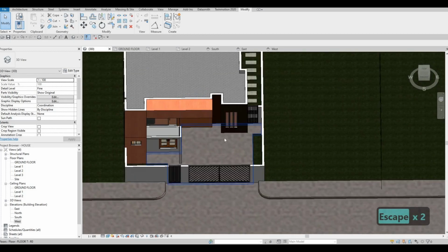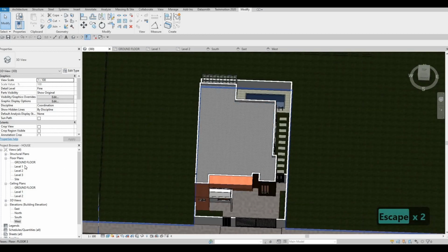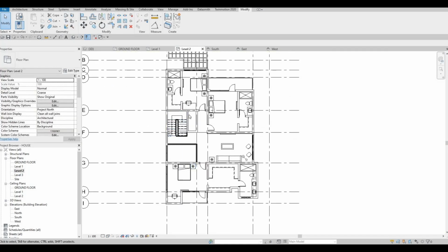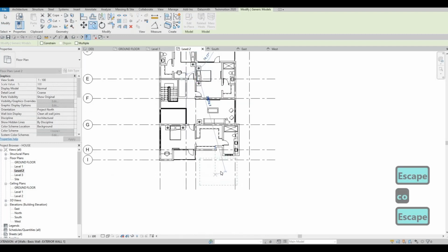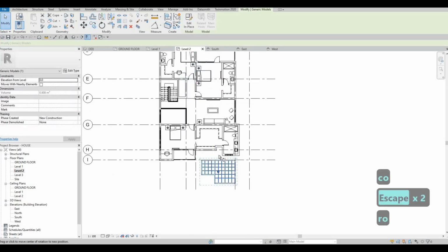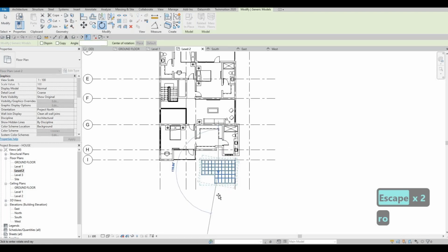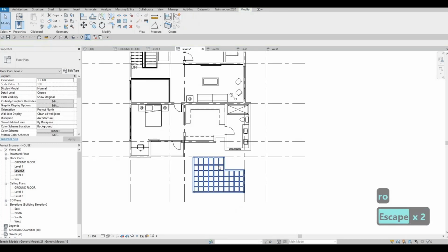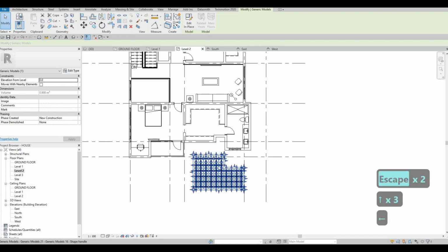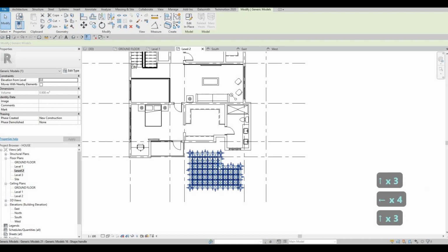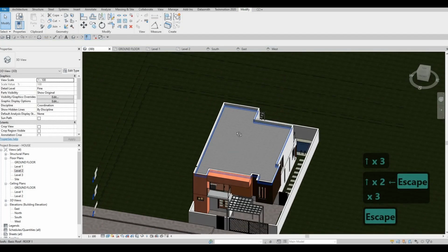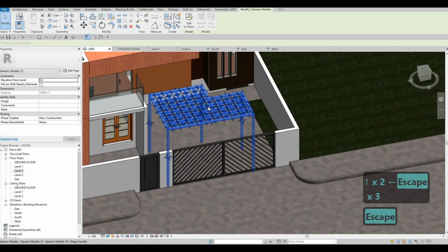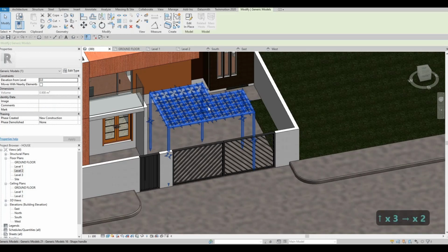before that, I want to extend this part. So here we have, so let's go to level 2. We have this one that we created in the backyard. I'm gonna copy that, and then I'm gonna place it here. I'm gonna rotate it, RO to rotate, and then I'm gonna rotate it right here. I'm gonna nudge it in place so that we have it on this location, and then we're going to extend everything else. So right now we have something that looks like that.